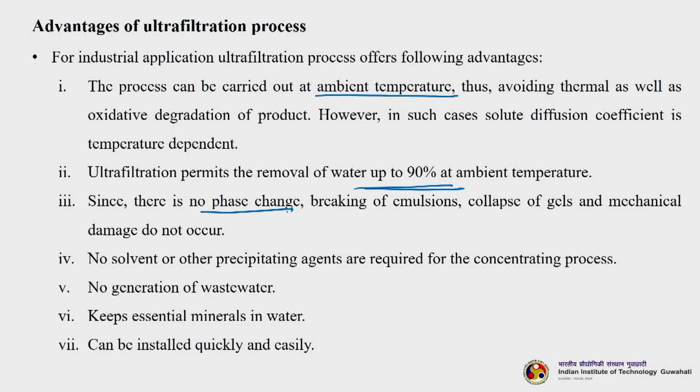So, breaking of emulsions, collapse of gels and mechanical damage do not occur. No solvent or other precipitating agents are required for the concentrating purposes. No generation of wastewater. Please, this is one of the things which you can compare with RO, reverse osmosis. There is a RO reject, right. So, here there is no generation of wastewater. It keeps essential minerals in water unlike your RO, and can be installed quickly and fitted easily.